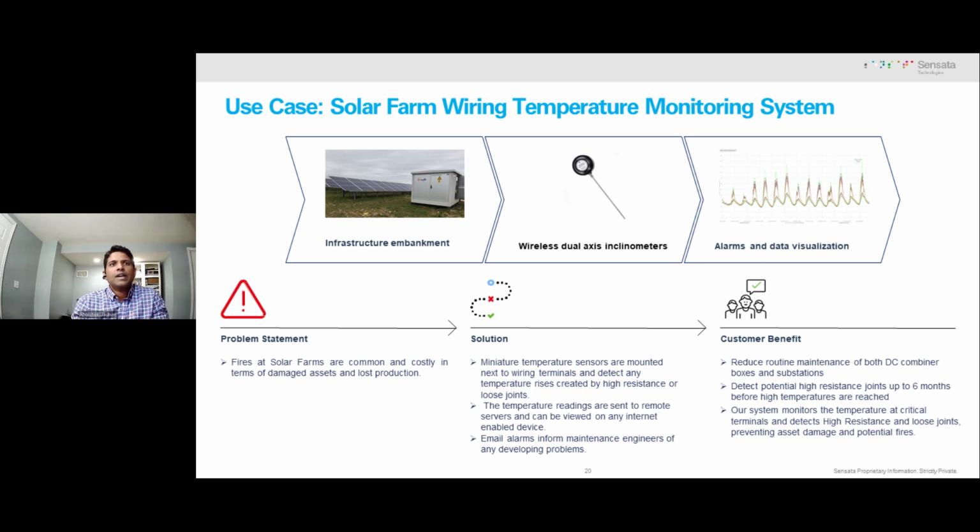Even if thermal imaging is done regularly, it does not provide continuous, reliable, or predictable data. This data scarcity makes it harder to analyze and trend any sort of joint failures, which occur mostly in the peak summer hours when you're not taking any measurements. And then the high ambient temperatures in the summertime cause production loss because of the increased joint temperatures.